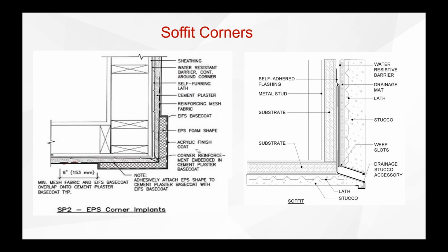Okay, this is another one. This was a project that I was working on, and this was a parapet wall up here. There's a window over here. I was spraying water over here, and I was getting water over the top of the window on the interior side. I couldn't figure out why that was happening. What happened is this water was coming down here. This was a foam band, it couldn't get out, so it started tracking back, and it eventually dropped over that window. So again, back to my point, you always want to keep these panels separate.